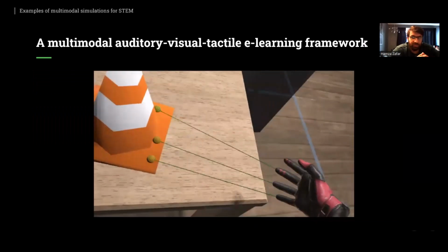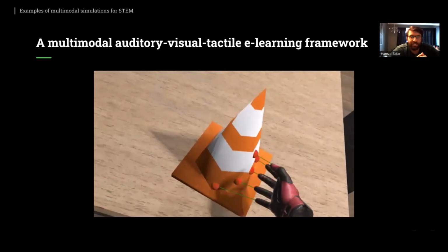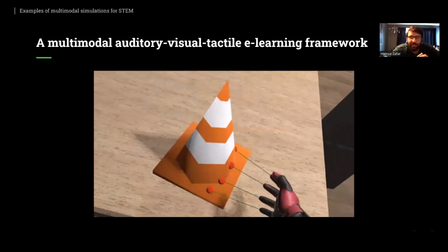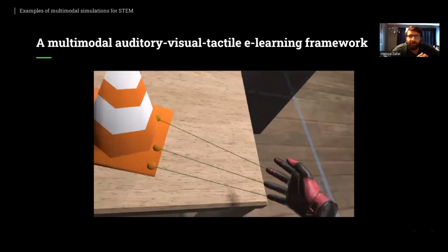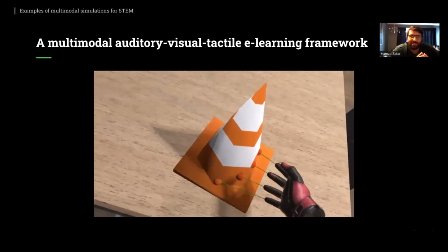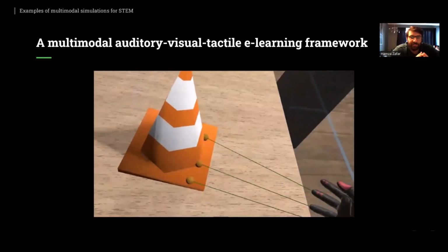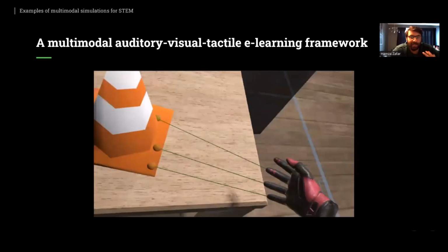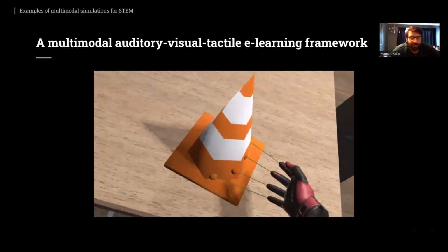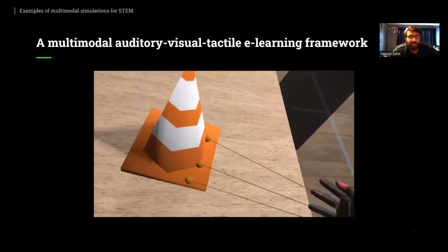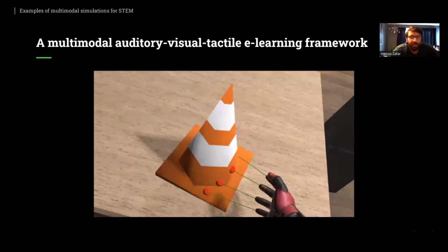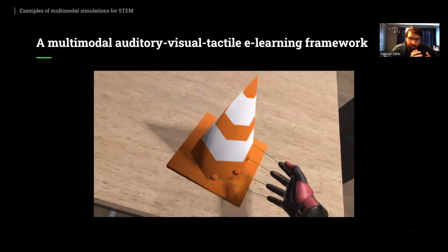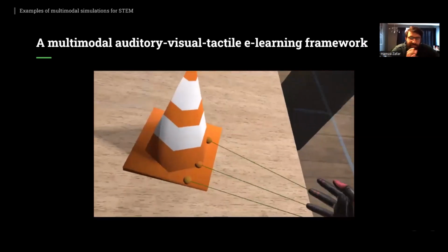The implementation of finger ray casting for collision detection is shown here. For each finger, a ray is cast from the fingertip in the forward direction against all objects colliding in the scene. Then the interaction forces to be rendered are calculated. Three distinct feedbacks are provided. Regarding haptic feedback, the force is rendered by using a pulse width modulation signal where the duty cycle of each vibration actuator is proportional to the force to be rendered, normalized between the specific actuator range.